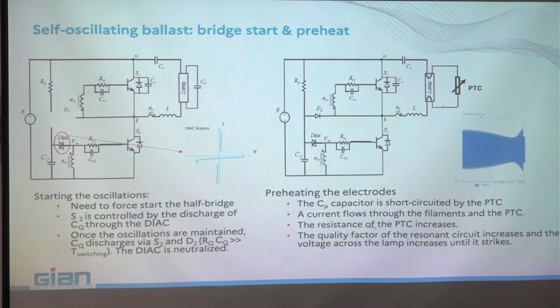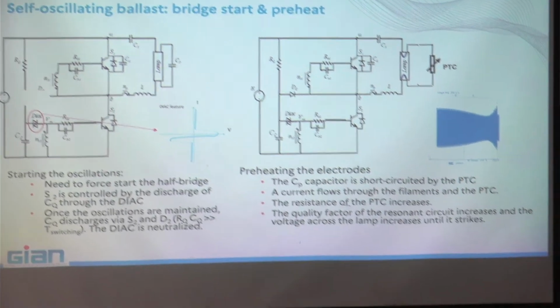As I told you, sometimes for this kind of lamps, but also for high pressure lamps, if you don't send the right wave to the lamp, the right voltage, especially during the breakdown, you can cause evaporation of the materials that are on the top of the electrodes.